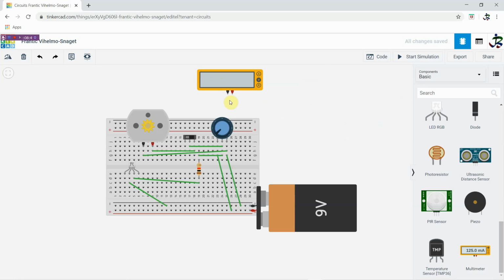So let's consider this is positive. The voltage across which you want to measure, how much voltage is going. I want to measure the LED voltage, how much voltage is there at the blue LED terminal. So I'm starting this. Right now only 7 millivolts is going inside. So I'm increasing, or decreasing, I can say. As I increase the resistance, the output voltage going to the LED is decreasing, and that is the reason a very dim LED is glowing. Now again more, now it is 0. So that is the reason there is no power.